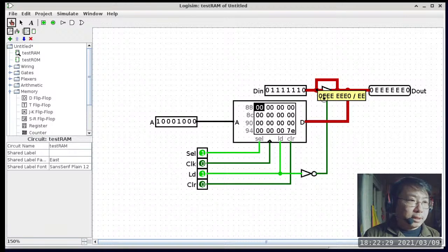Because they're not agreeing on what the state of that pin should be. So in reality, what happens in a bus fight? In a simulation, we can basically just say, oh, the logic sim identifies that we have two outputs. One output wants to specify a 1, the other output wants to specify a 0. So we have an erroneous condition here.